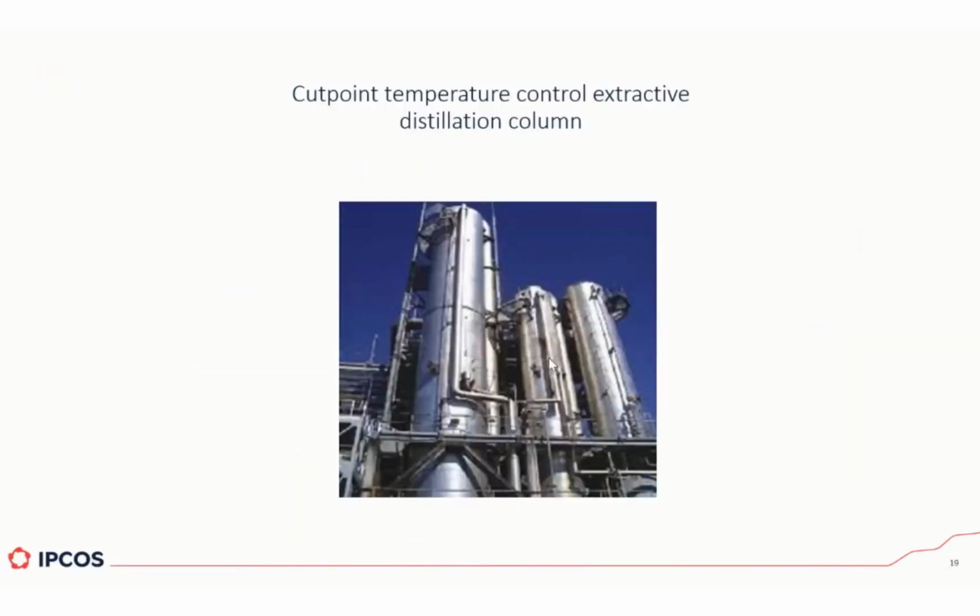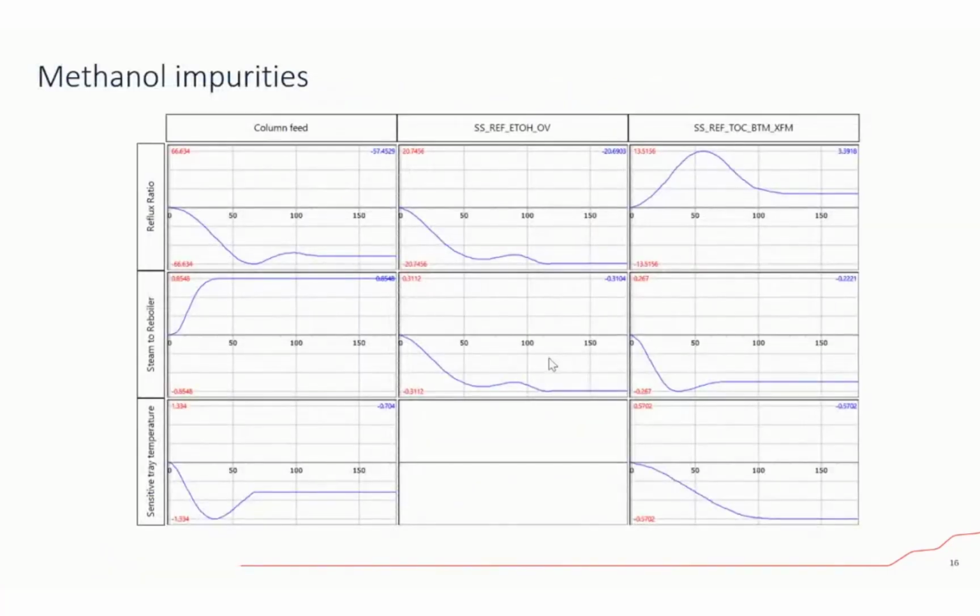Right? Hey, JC, one quick question before you go to the next one. Somebody asked, what is the time to steady state in this column? And how does the percent impurity in the feed change? Yeah, the time to steady state, as you can see, is roughly 3 hours, give or take.